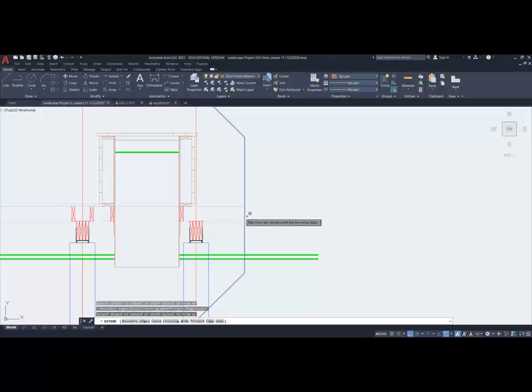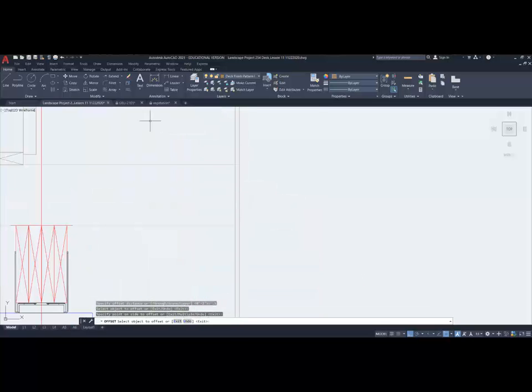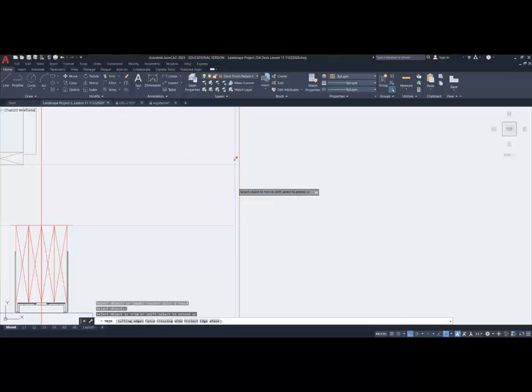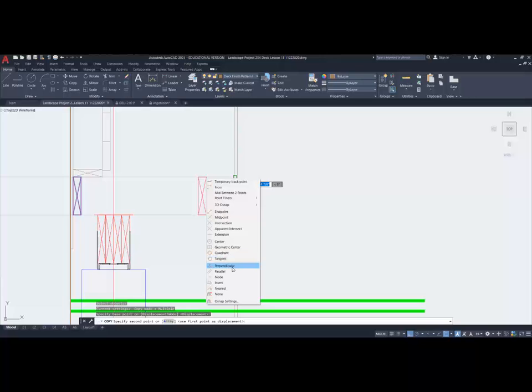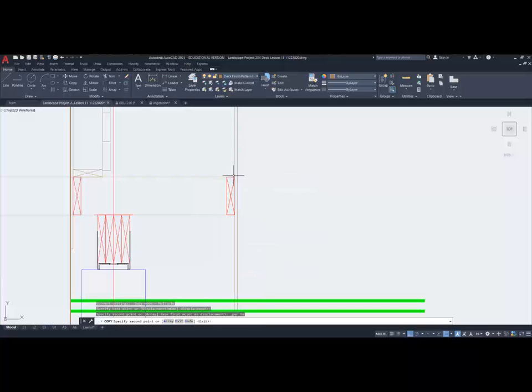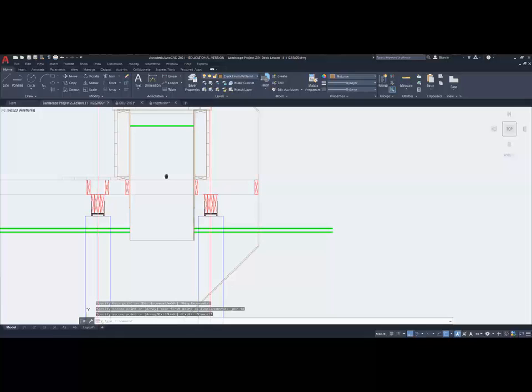that, and that. And I have a 1/2 inch overhang, so I'll offset 0.5. Move that inwards. Trim that at this point. So the decking itself will go to that end. There we go. I will copy this. This will now be my rim board around the perimeter. And I will copy these deck boards.